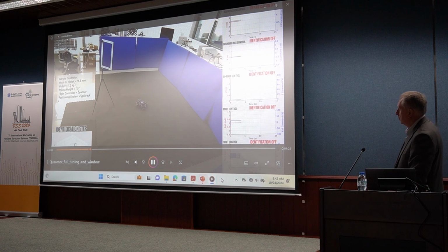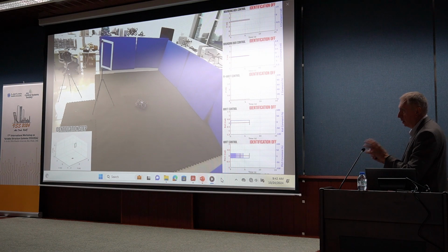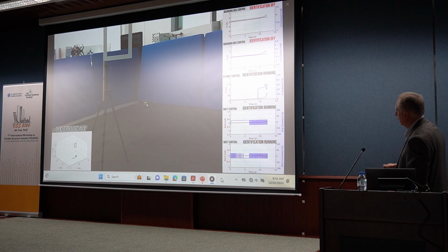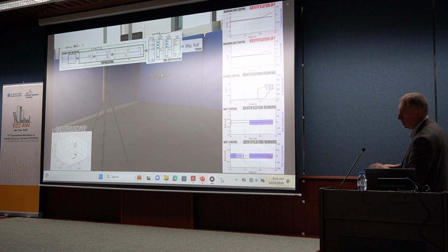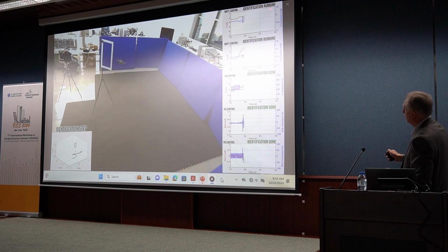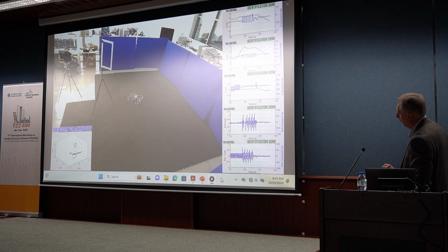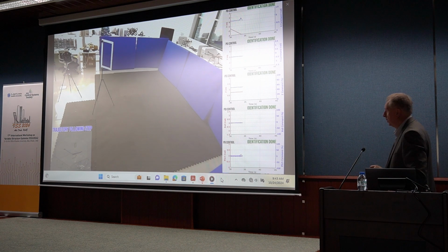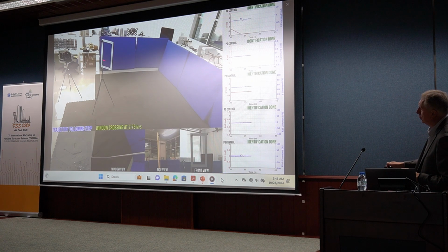you didn't see yesterday in a complete format. So it's untuned, and here 5 controllers are being tuned. Whatever is in green, it's completed. The tuning is complete. Now all 5 are complete, because here we have pitch, roll, Z, Y, and X. So these are the controllers that are being tuned. And now it passes through this window.